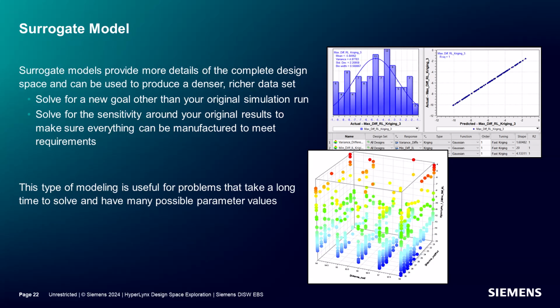A surrogate model solved for 10 times the number of points in a quarter of the time in one example, 750 points in about 27 minutes versus the normal 10 hours it would have taken on the initial run. The results can help the designer understand what trade-offs are available and what improvements are possible. Here, a 3D symbol plot shows relationships between antipad size and pad size against a return loss.